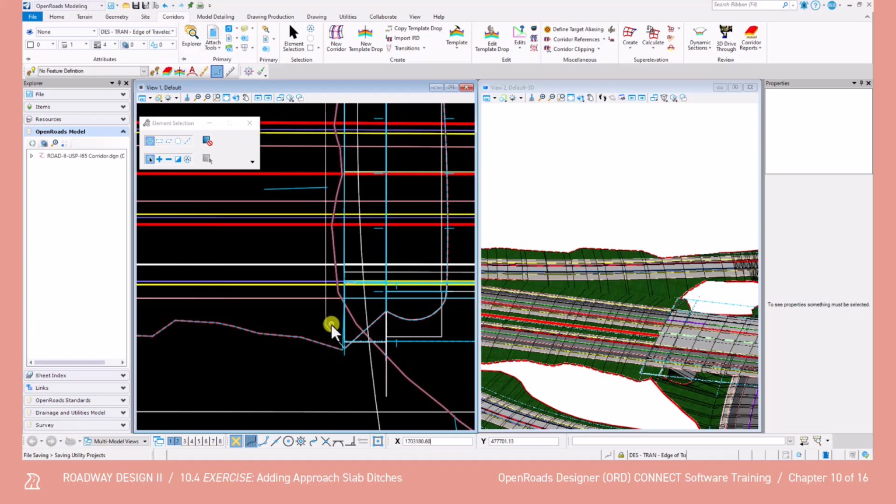alignment. So let's go ahead and select the match line control feature definition under linear, roadway, model control 2D plan, and then match line, and toggle on the create 3D automatically. Note that a controlling line must be placed to define the location of the civil cell. The naming convention of the civil cell relate to the location of the ditch relative to the bridge and the current view.